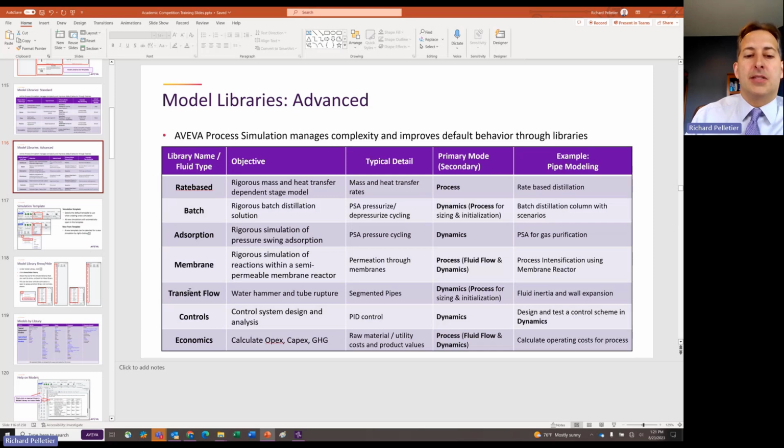And what ends up happening is you see these ginormous pressure swings due to basically dead ending a flow from completely shutting off a valve or something similar.